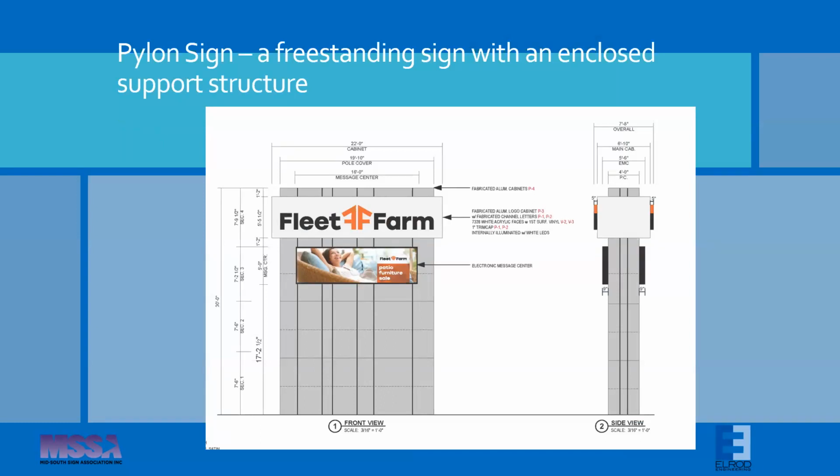But one of the things that quickly became a point of concern for the design of this was the actual framing of the cabinet itself. It's large enough that you might need to verify, or you might be required to verify, that the frame works out. Roughly 600 square feet of cabinet. And so all that framing is receiving a pretty significant wind load. And so we did an analysis of this to make sure that it wouldn't buckle under the wind conditions and take care of our client by watching that for them.